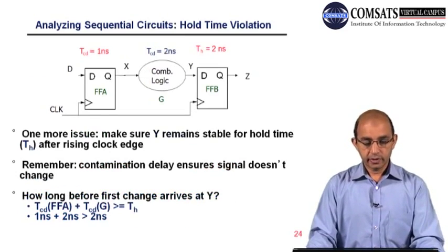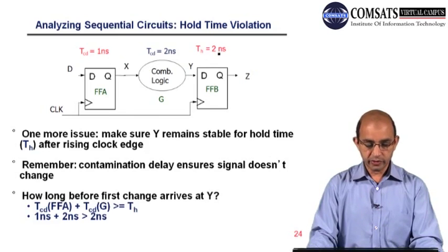Okay, so let's talk about the hold time. Here we have the same circuitry, with TCD 1 nanosecond, TCD 2 nanoseconds, and TH 2 nanoseconds. As we have mentioned, in the case of sequential logic, the input at the flip-flop, or at the sequential circuit, should remain valid until TH, that is the hold time.